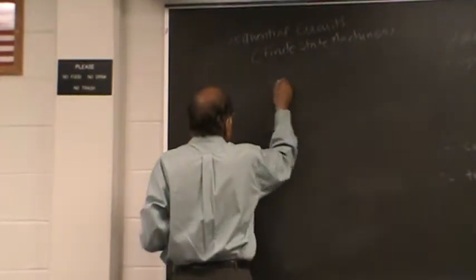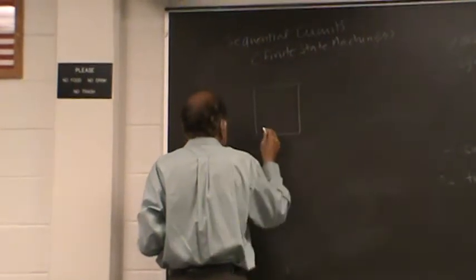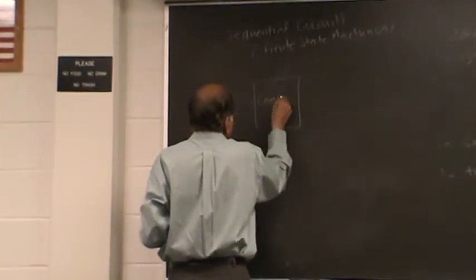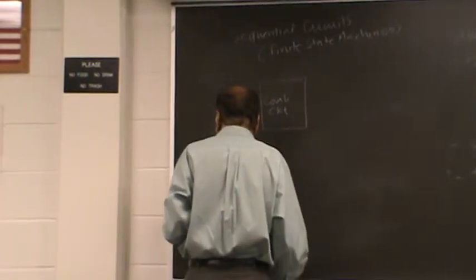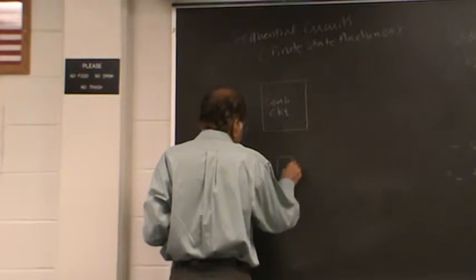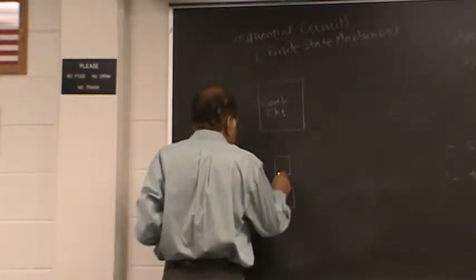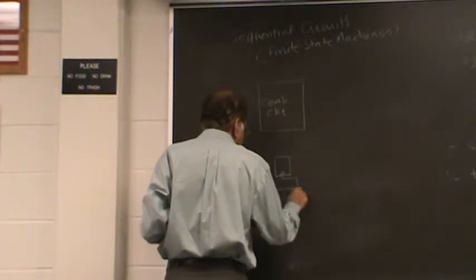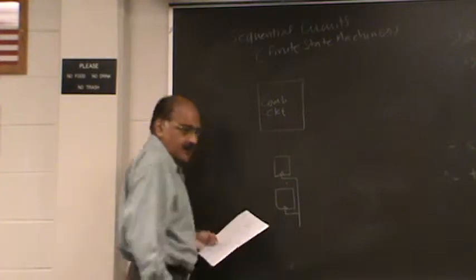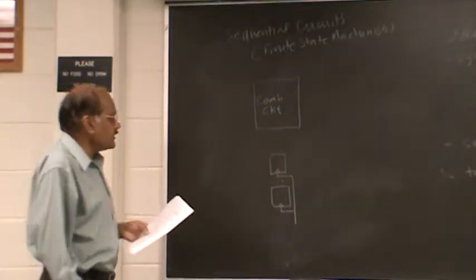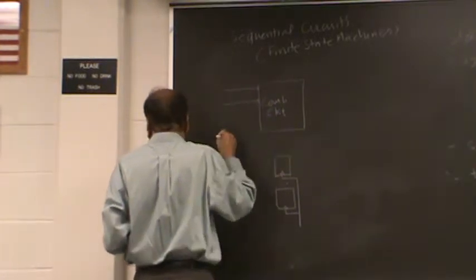Now, finite state machines, synchronous sequential circuits: one part of that is some combinational circuit, and this combinational circuit feeds some storage elements. Let's assume that we have a bunch of rising edge triggered flip-flops. Here we have the external inputs.